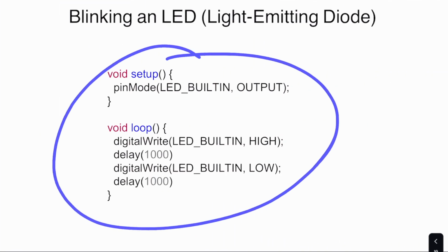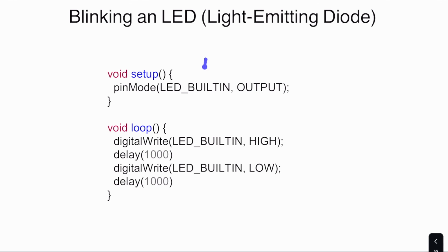into this. They also have standard names for things, so you can pick up an ESP32 or an AVR, one of their line of microcontrollers, and if you're using Arduino, you can just say all caps LED_BUILTIN, and if that board, that particular board, whoever it's developed by, if it has a built-in LED, that pin number will be assigned to LED_BUILTIN. That's part of this ecosystem.